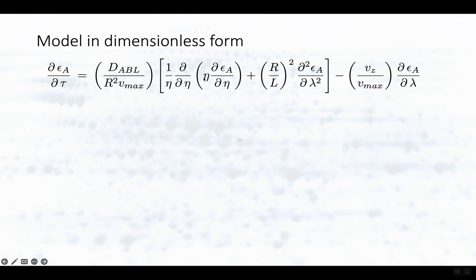Now here I've got the axial diffusion term, but I've got a multiplier, a dimensionless ratio here of the inner radius of the pipe, the maximum radius of the pipe, R, divided by the length. Well, if R is small compared to the length of the pipe, then this number is less than 1, and I'm squaring that number, so it's even further less than 1.